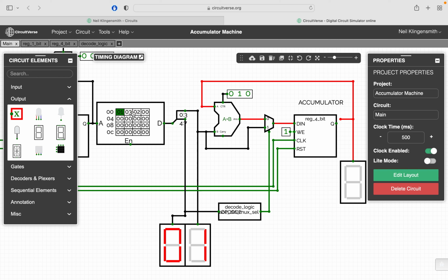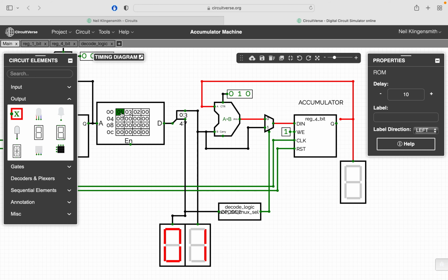So you can see all of the instructions in my instruction memory right now. These are all add immediate instructions. If I want to do a load immediate to the accumulator instruction, I'm going to put a 1 in the first nibble. So let me make this 1F. The first instruction now is going to be 1F, which is instruction opcode type 1. That's a load immediate into the accumulator. And the immediate value that's going to get loaded is F, right? 4 1s.